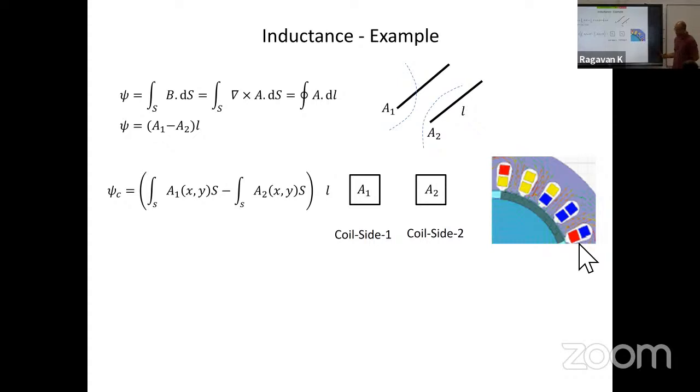Okay. So by default, every FEA solver has this kind of post-processing code that evaluates the inductance. It gives a test current and gives you the inductance. So let me take an example of an induction motor, right? I have created an induction motor and I've also modeled the squirrel cage bars.